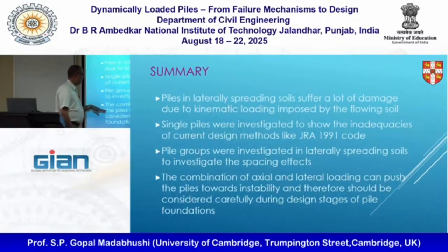The main point that I wanted to convey, and this is really the crux of the matter, is you cannot take piles in liquefiable soils and demarcate them as ones which carry axial load and ones which are subjected to lateral spreading. It's the same pile carrying the same load.